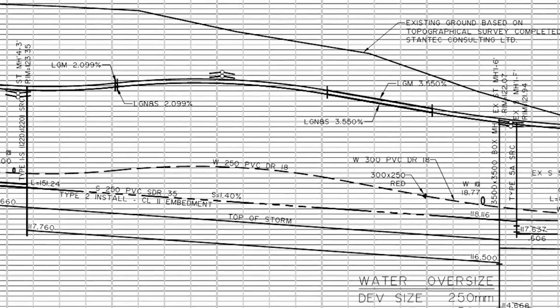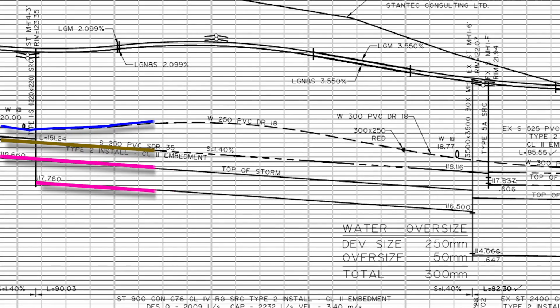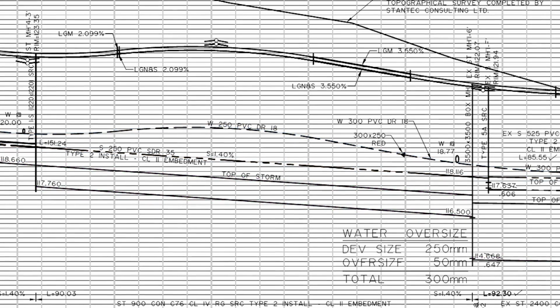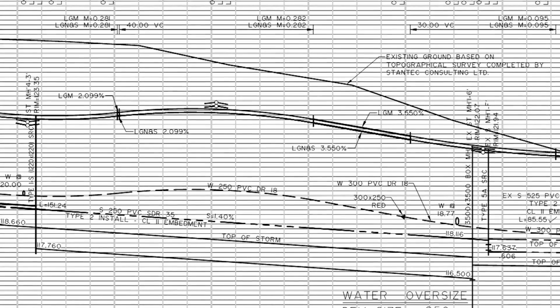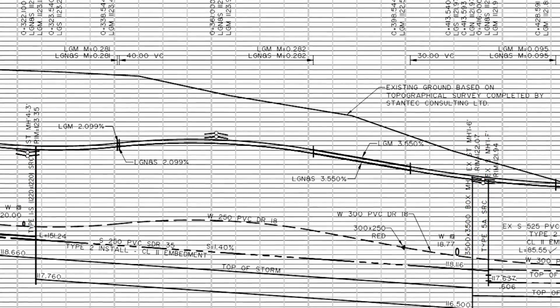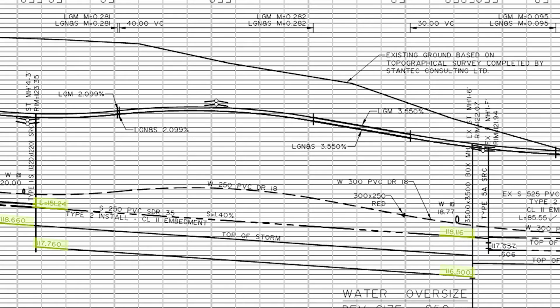Below the lip of gutter lines, we see the lines for water, sanitary, and storm pipes. They are all labeled with their size and type like on the cover sheets we saw earlier. The lines for all pipes refer to the invert line unless otherwise noted. Again, the invert is the bottom of the pipe. At each manhole, you'll notice the name and rim elevation, as well as the type of manhole listed on the vertical line below. At the bottom, you see the invert elevations also.